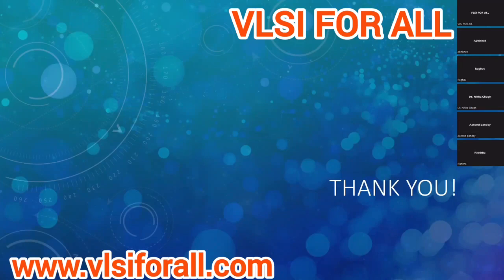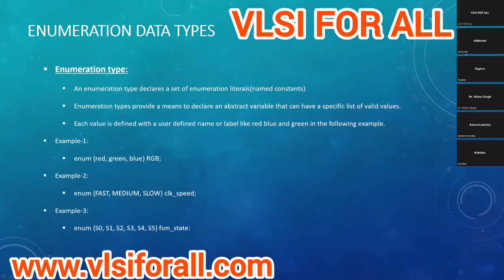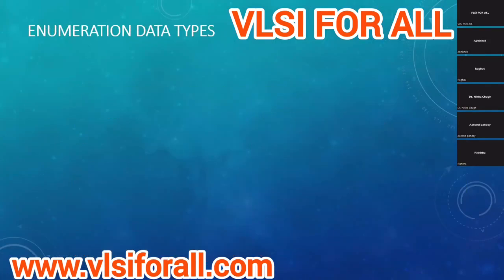Sir, one question. In the data types, you were explaining some output, and you said that it is 4 state, although it was not defined as logic or bit. So how is it 4 state? Can you open that slide? Okay, one second. It's basically inferred. If you don't define it, it will be inferred as 4 state.